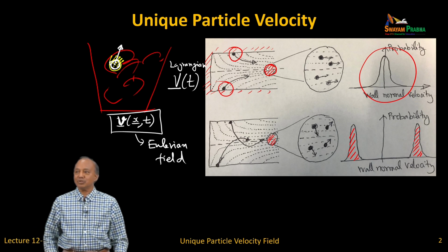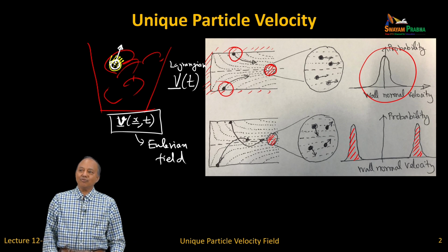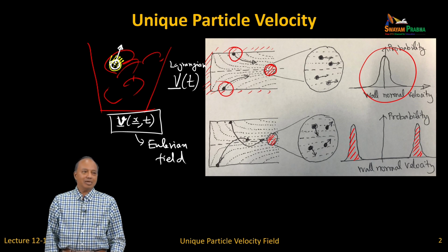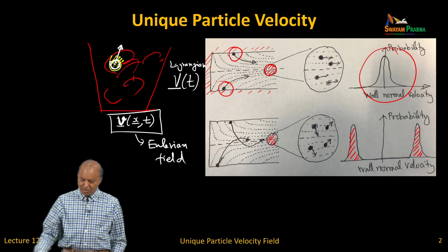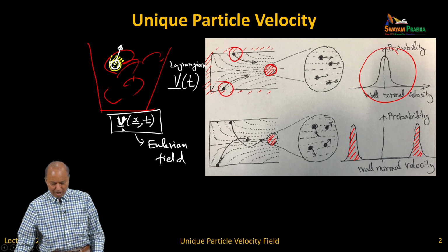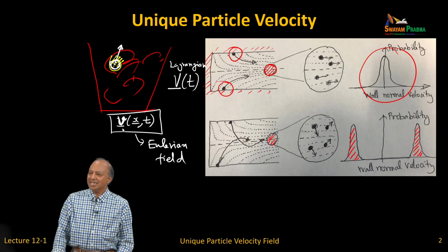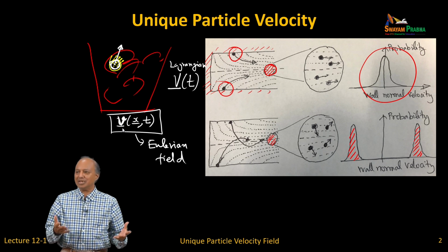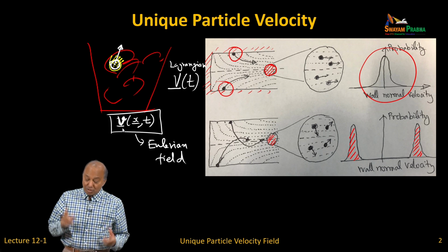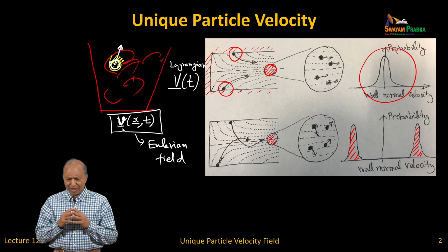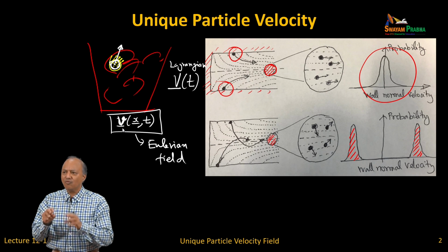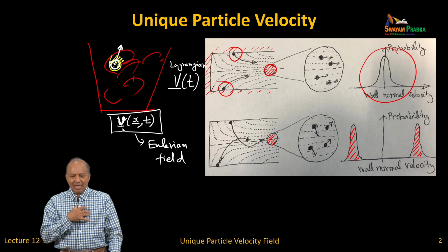Now, the Stokes number is globally defined, that means the worst case fluid time scale anywhere must be still bigger than the particle time scale. If that is the case, then when you use Euler, you can be safe in saying that, yeah, I do not have this kind of crossing pattern there, all the particles are nearly going together. So the main thing is that I want to differentiate one thing. I am not saying that the particles will move lockstep, I have to be very careful.